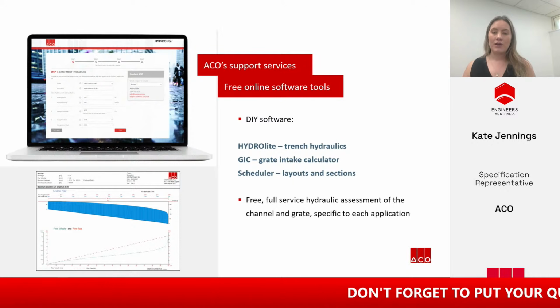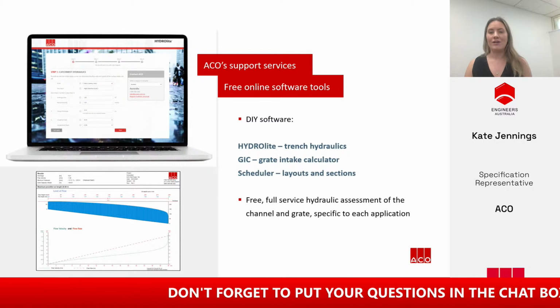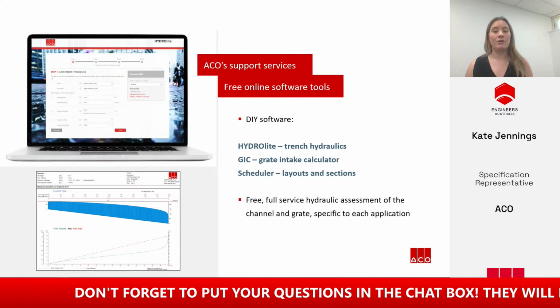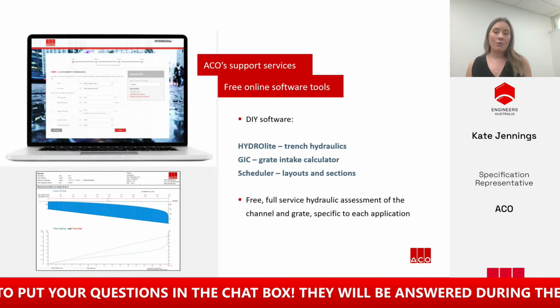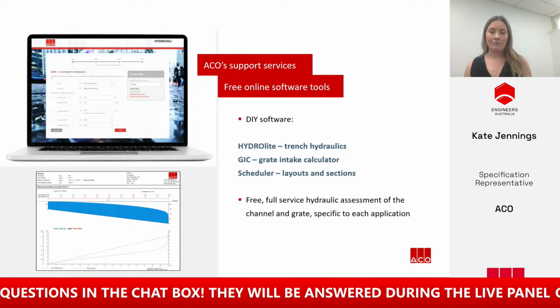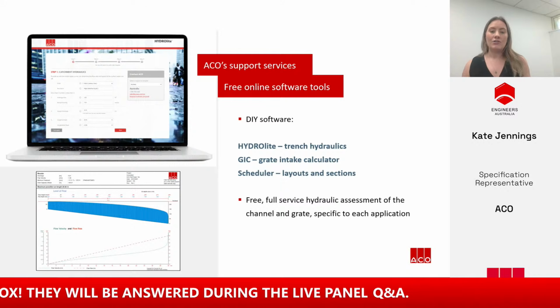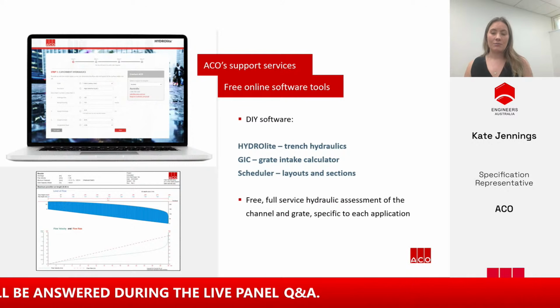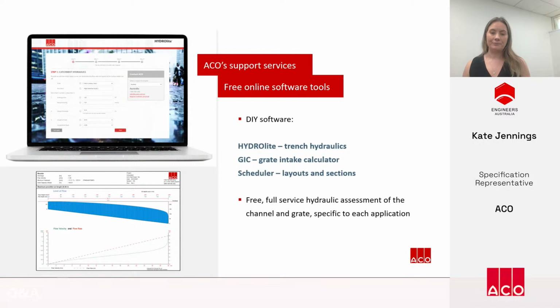Beyond our products, we also have a lot of support for designers, both with online DIY channel and grate sizing programs and tailored product support from our technical services engineering team. These DIY programs are a fantastic way to get really quick information on hydraulic performance of channels and grates. Hydrolite is our channel sizing program, and GIC is the grate intake calculator. Both of these are grounded in experimental test data.